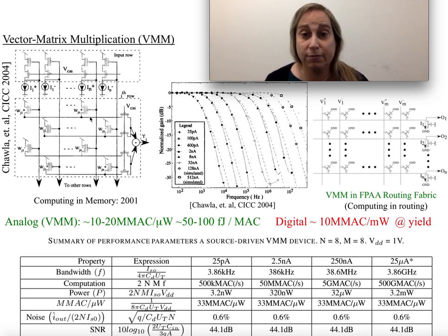You can then do things as in this structure, which was designed to make sure I had a perfectly good four-quadrant multiplier. So I could have a signed input and, with four transistors here, get a signed output. And I could do this in a large array, a whole linear array of these, and do all the measurements around it.